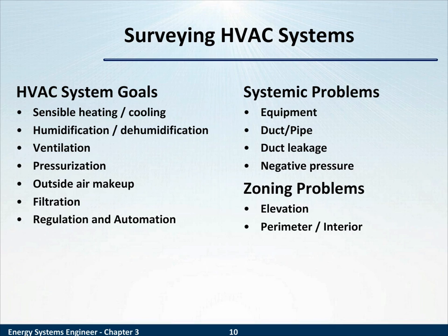We'll look then at ventilation, the pressurization, meaning if, say for example, a door was open, would air in that building blow out the door, or would the air be sucked in through the door? Is the building positively or negatively pressurized? We'll consider outside air makeup. In some respects, to achieve a building code requirement of a certain amount of outside air. When you survey the system goals for HVAC, you also have to include air filtration. And then lastly, the regulation and automation of the system.